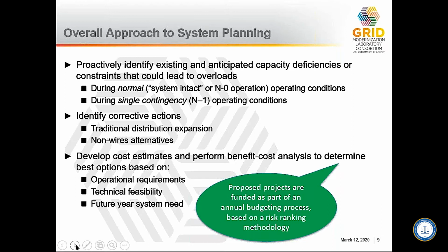So an important aspect of planning is the process of analyzing the system's ability to serve existing and future customers by evaluating the historical and the forecasted load levels and the utilization rates of equipment, such as transformers and feeders. Xcel Energy and most utilities that have high DER penetration see this changing as the planning process evolves from just analyzing future loads to analyzing future electricity connections, which include DER, electric vehicles, and other non-traditional loads. And so as the planning process evolves, non-wires alternatives to DER become a major part of the challenges and the opportunities for distribution planning. Next slide, please.